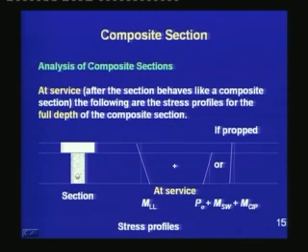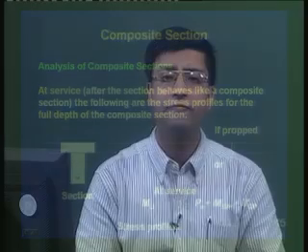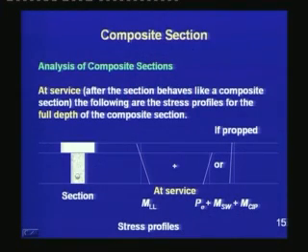At service, after the section behaves like a composite section, the following are the stress profiles for the full depth of the composite section. Now we are moving on to the service load stage. By the time the flange has hardened, the full section can now act as a composite section. Hence, the additional load that comes during the service period is shared by both the web and the flange, because the full section is acting like a composite section. Thus, the stress block is such that the moment due to the live load is carried along the full depth of the section,